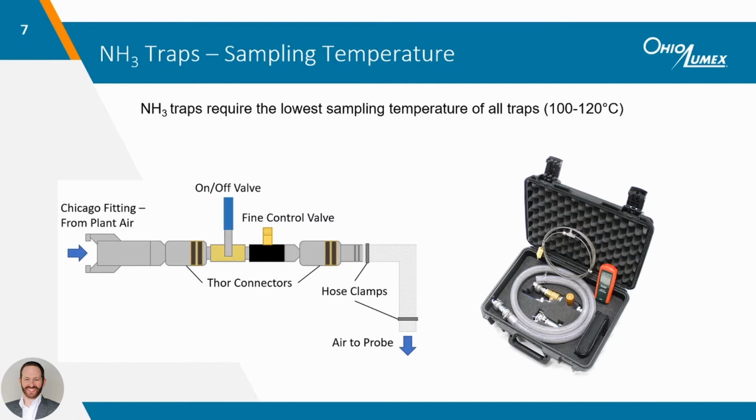The problem is, pushing cold air through a probe that is constantly being heated by duct gas creates a situation where the probe is not at a uniform temperature. Therefore, a standard built-in trap thermocouple is not likely going to measure the real temperature of the sorbent, even if it's only a few inches away from the trap. Additionally, it can be very difficult to find the right amount of cooling air to ensure a stable probe temperature